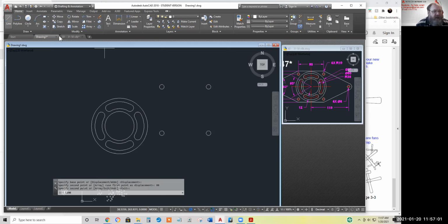I'll draw a diagonal line from, say, center of this one to center of that one. Now with this guideline, I can move all 4 from the midpoint here to the center there. Move, select everything. I'll erase the guideline later, hit enter, grab the 5 items from the midpoint of the guideline and hover, O-snap. There we go. Now I can delete